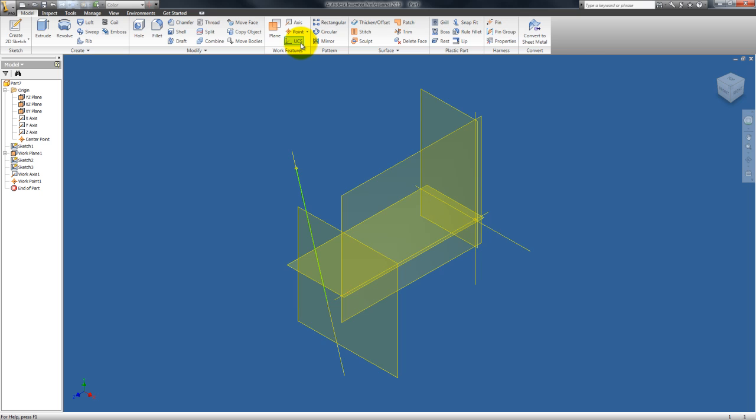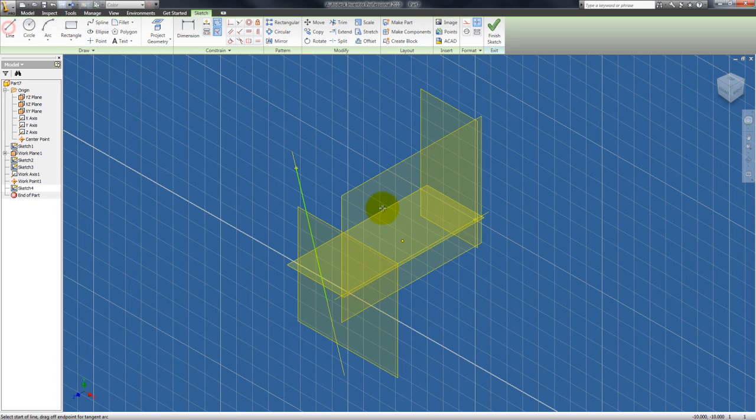Final thing to cover is UCS. So the default UCS, its user coordinate system is what it stands for. So the default is, that's the origin, and then we've got our Z, X, and Y axes, and then their corresponding planes. But if we want to change that up, let's actually, I'll show you a real example of this. So if we go back and make a sketch here,